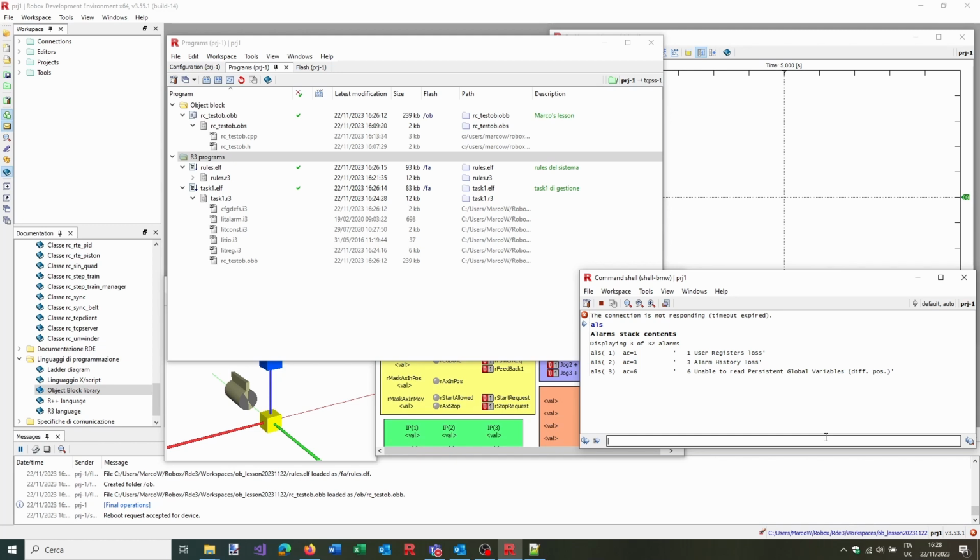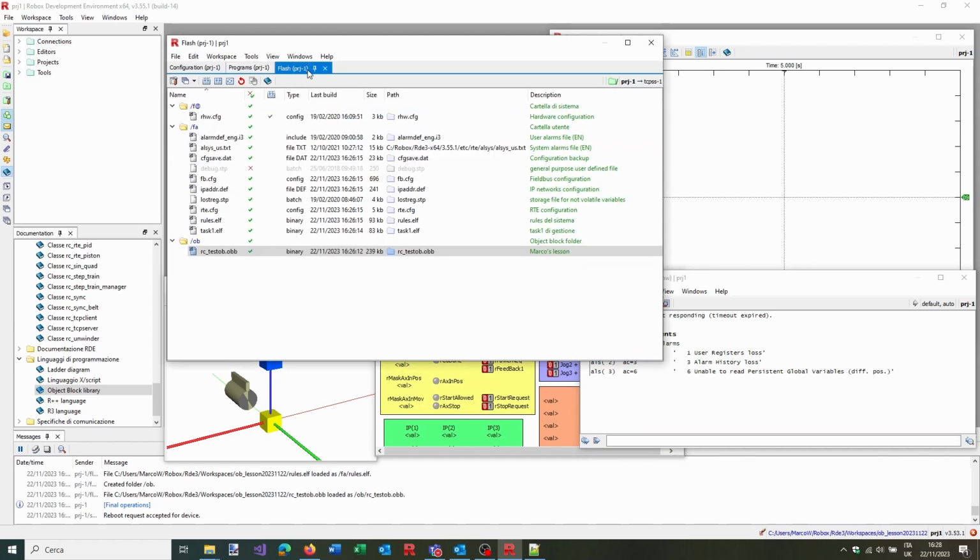If now I press 3 times the advance, I will accept these alarms and I will reset them. In this way, the controller will understand I really want the new project to be taken into account, so everything will be erased to start from 0. All the non-volatile registers will be reset. And then, the lost reg file, if present, will be executed at once.